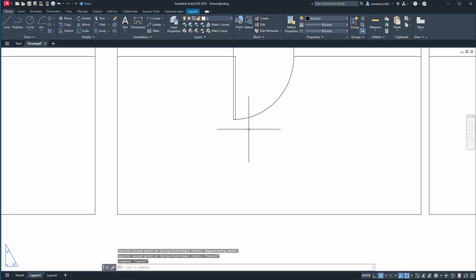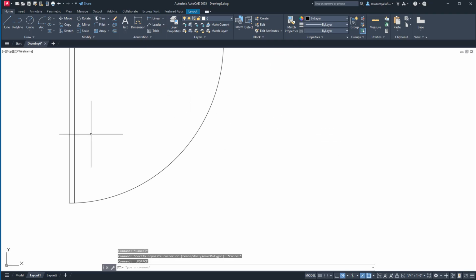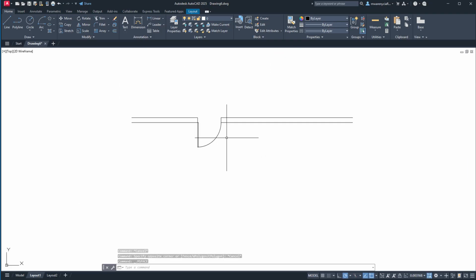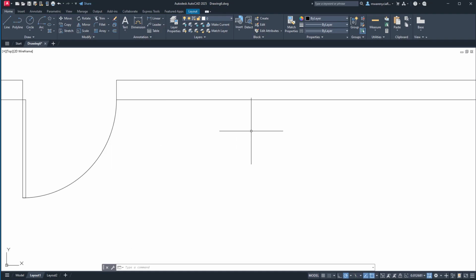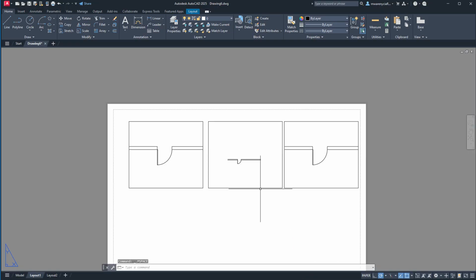And then let's say you want to go in here to change this. You double clicked, and oh, well, wait a second. Now I'm stuck in this viewport. If I zoom in or out, I can't, because I'm zooming in the viewport. I don't have an area outside of it to click on. All you have to do to get out of this is click on this thing that says model right here, and it snaps you back to paper space, and now you can zoom out.